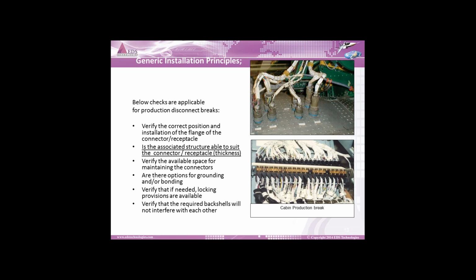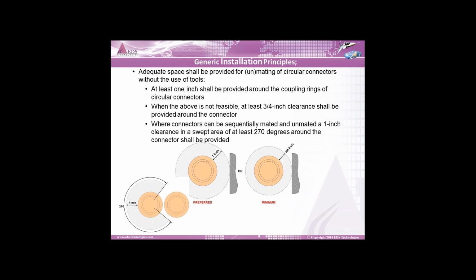Very important is to position your components, your patch connectors, and grounding equipment in a systematic format. What is the typical process? For example, I'm just giving you a preferred 1 inch from the surface, 1 inch minimum. This should be the standard. Each and every OEM has its own standard. You can fix those standards, that from the cable, this should be the position.